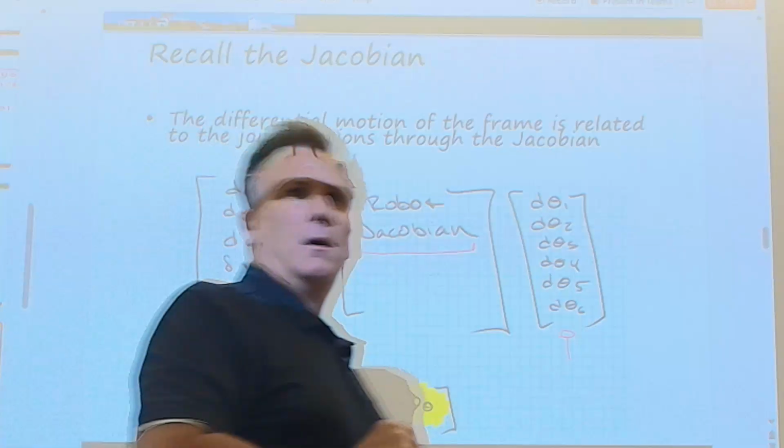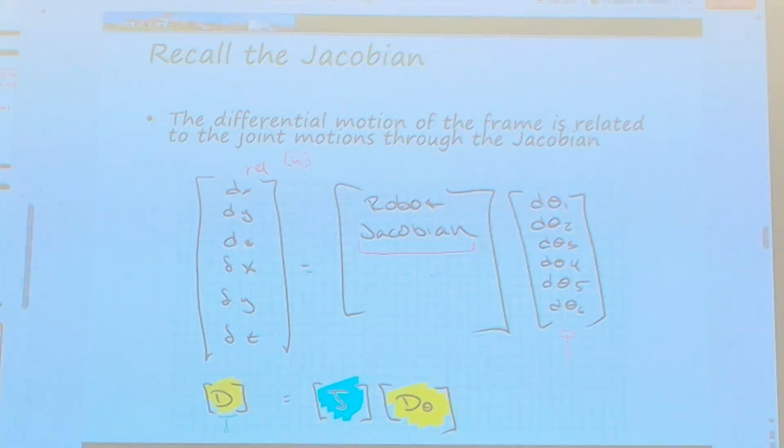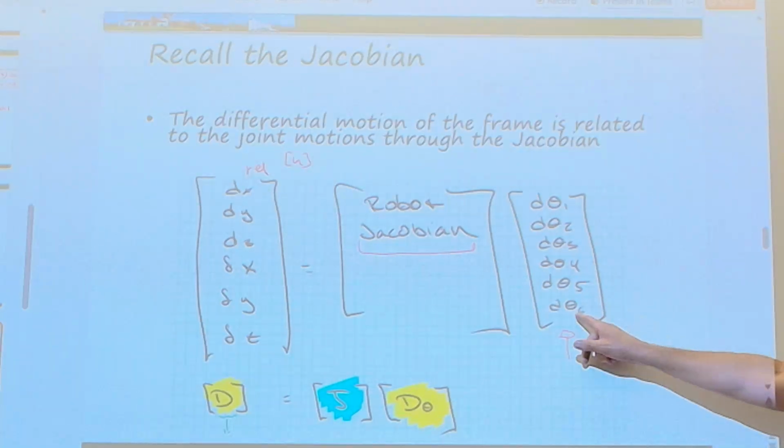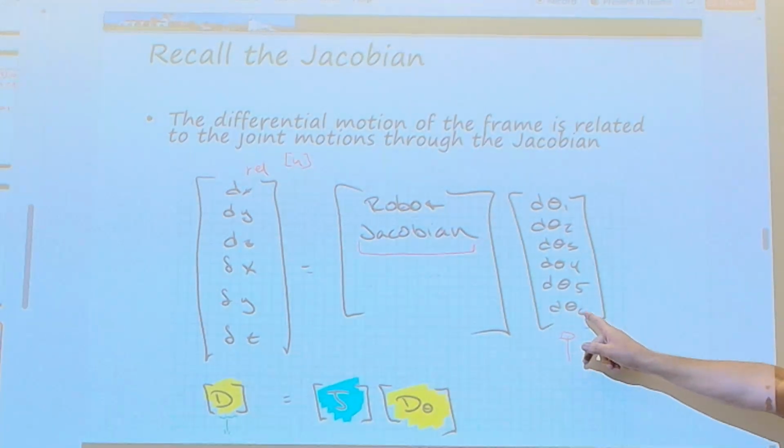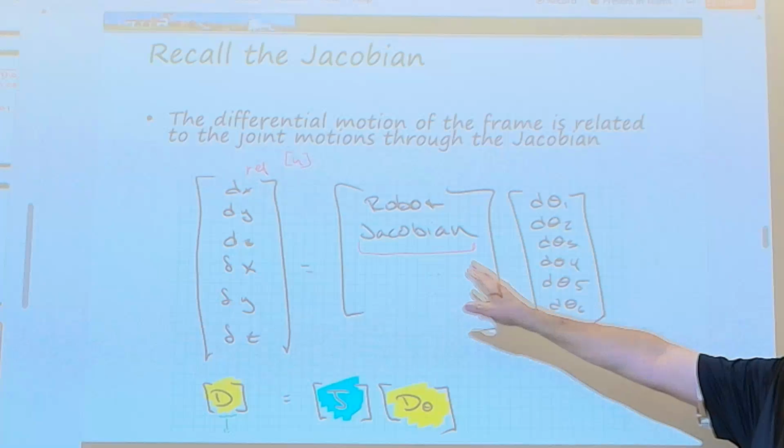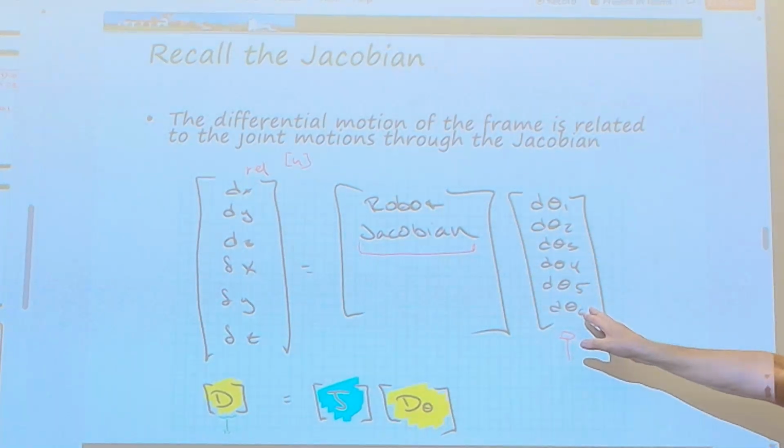Because you're speaking on the general motion of the joints. When you control the velocity, you can determine how fast you move to that point. So there may be some case where you need to move faster or slower, so you don't have the jerking. You guys are kind of dancing around it a little bit, but let's look at fundamentally what this matrix is. That's a vector. Does the Jacobian relate position or velocity?